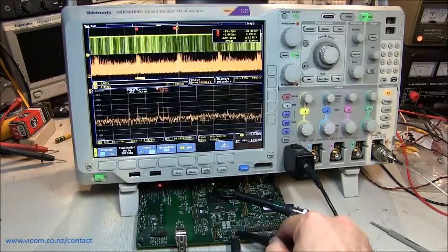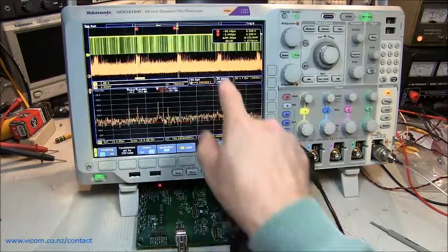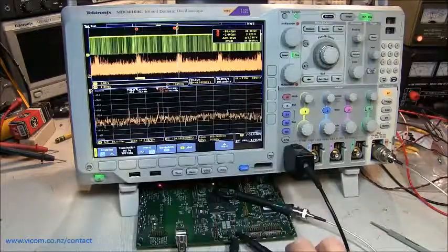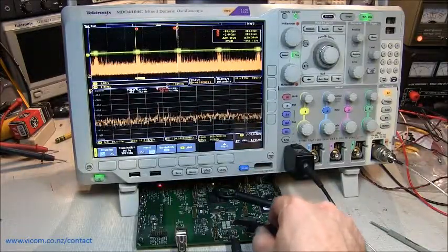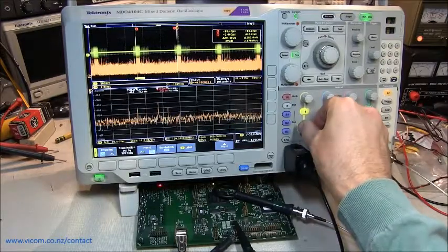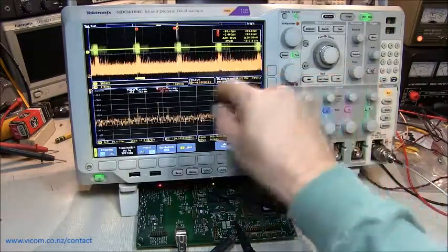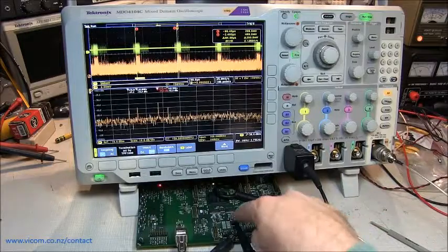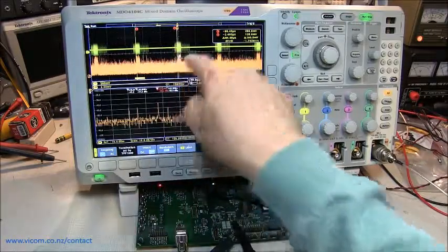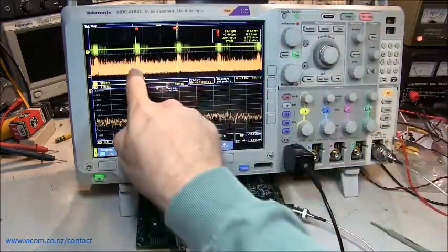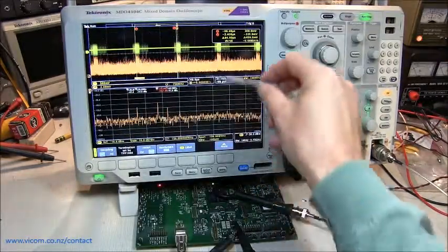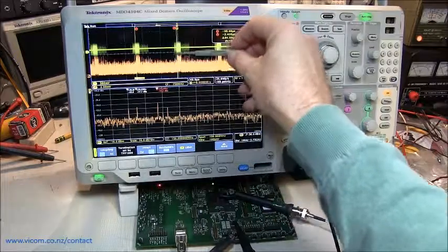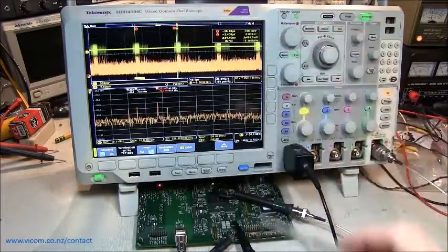Signals that are unrelated to the repetition interval of that event will appear completely random and free running with respect to the signal. But a signal that is coincident with that event will actually show up and be synchronous with that RF emission. So in this case, we've found a signal on our board that is occurring exactly coincident with our RF bursts. Identifying an electrical signal that is coincident with our RF emission is the key element to help you track down the ultimate source of this emission.